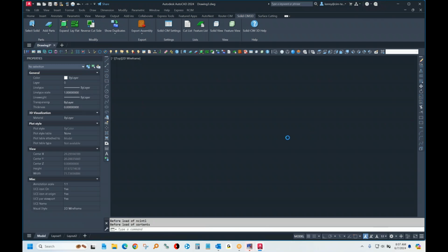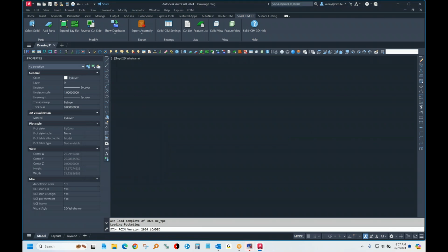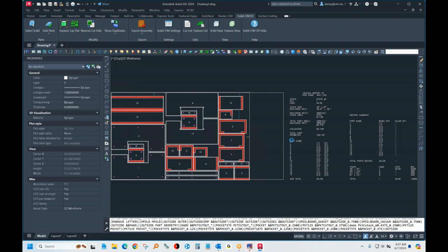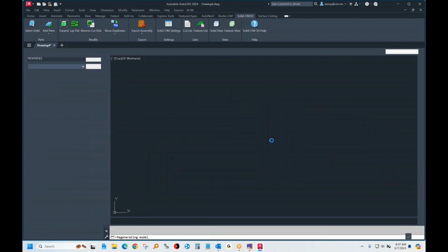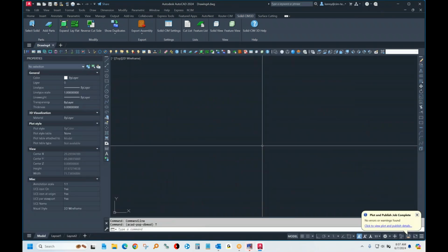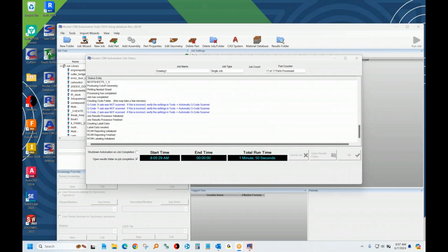And so I get the program for each one of those individual pieces, and now here's the nesting results with those different quantities. There's all the parts fit on the sheets. There's a scrap cut here. It cuts this off and saves this for next time. And it just finished the entire process in 2 minutes and 2 clicks.